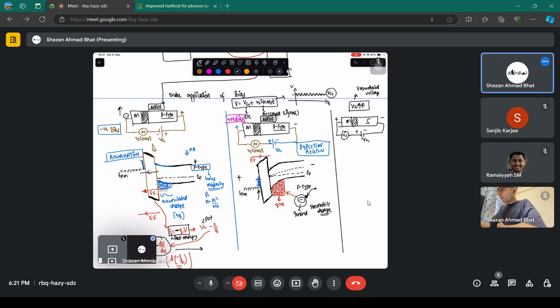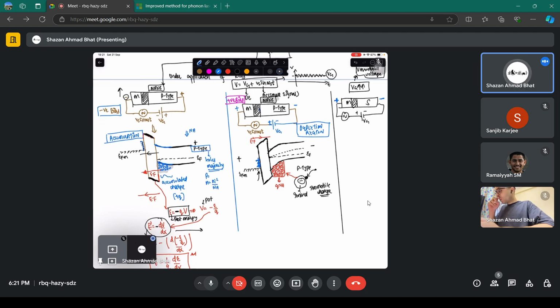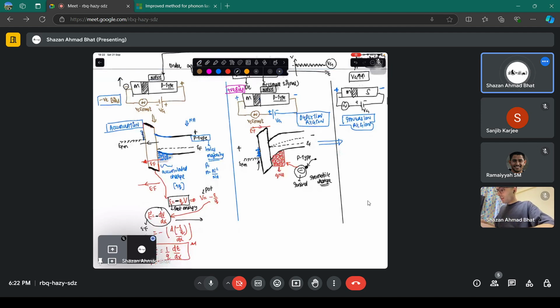Threshold voltage. Now, what happens because of increasing VG beyond this threshold voltage? The voltage you are applying, you are increasing it so that it moves out of the depletion region now. Now it goes into another regime, and this regime is called the inversion regime or region. Now, what happens in inversion? Obviously, it should come after this particular region. It happens in a stepwise fashion.